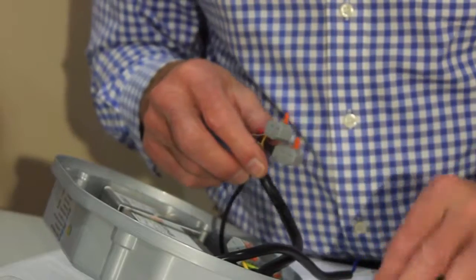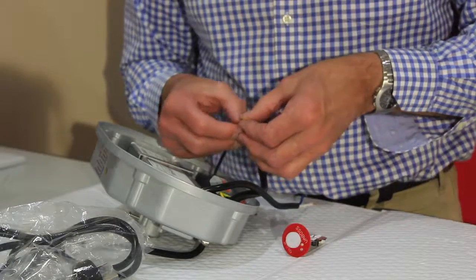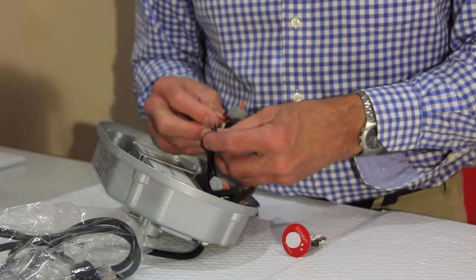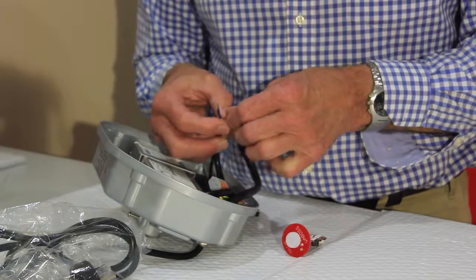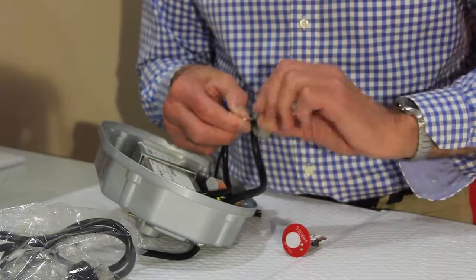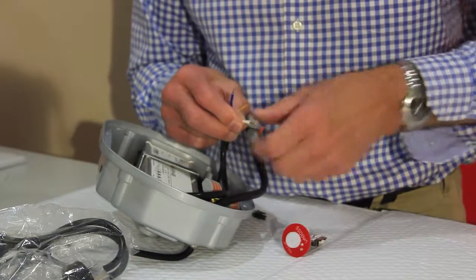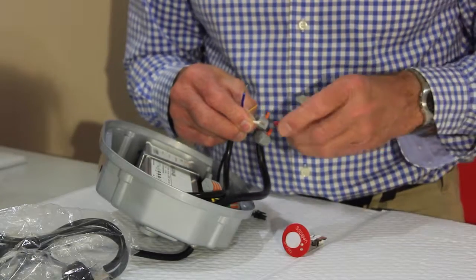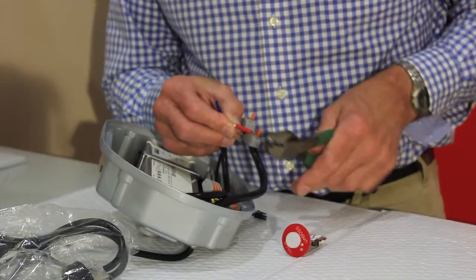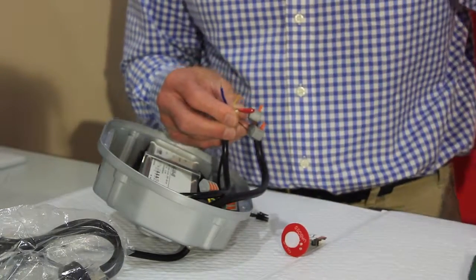The control unit is going to reduce 48 volts down to 12 automatically. Now the next trick is to take the control wires. Remember, the control is pole specific, so we have to have white to white, which is negative, like that. Put on a crimping connector like that. A little squash, crimp there like that.